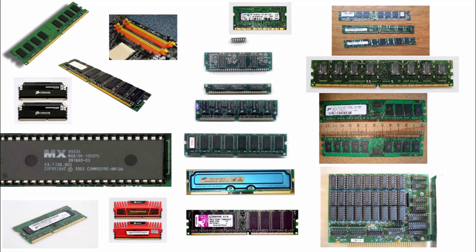RAM. A basic type of random access memory, indispensable in every computer, storing all or part of the currently executed program. RAM is volatile, which means that when the computer is switched off, the information it contains is lost. This memory is often called DRAM, dynamic RAM, because of its operating principle. Each memory cell contains a capacitor, capacitance, which, when charged to a certain voltage, stores 1 bit of data. The capacitor quickly discharges and the contents of the cell must be systematically refreshed by addressing it and recharging the capacitor. This process is called refreshing the memory and must be done cyclically.